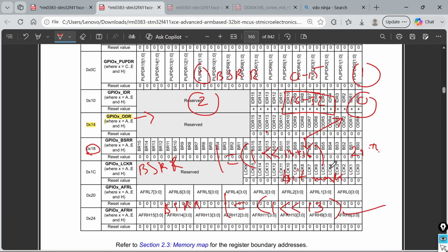Now the first way is the bit set reset register. Second is alias addressing, which is an ARM native feature, but some versions don't have this alias addressing feature. Okay. Now there are many other ways too, but they are section specific, say control block specific. But this is for the peripheral region.